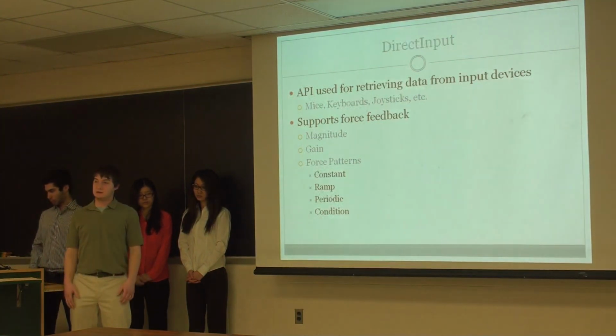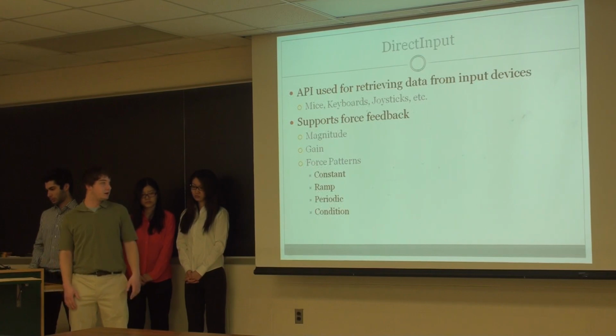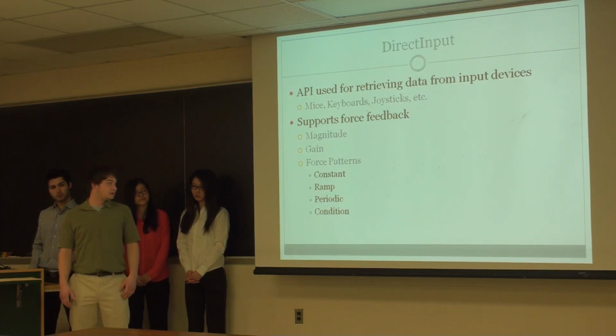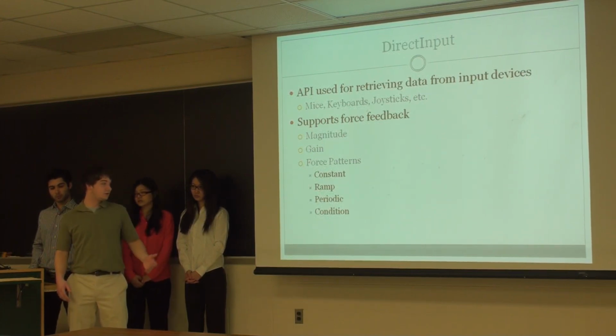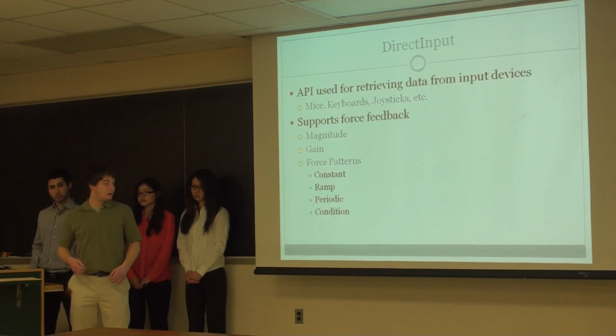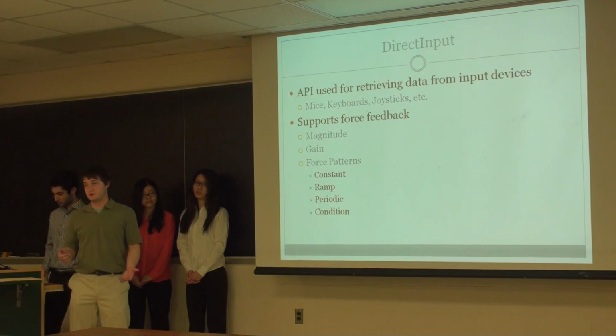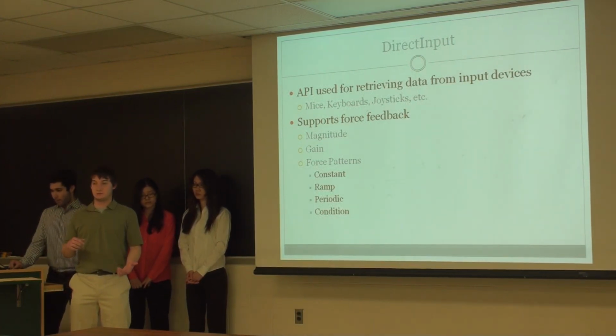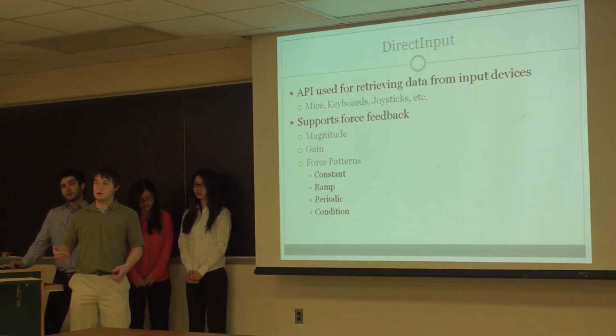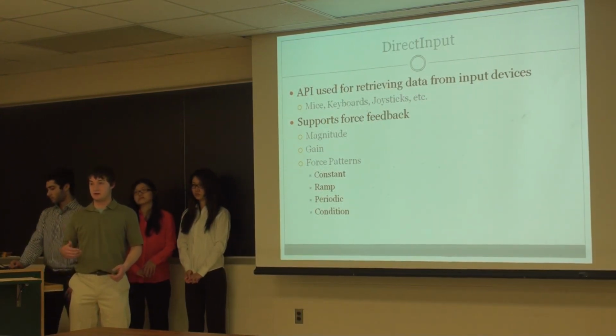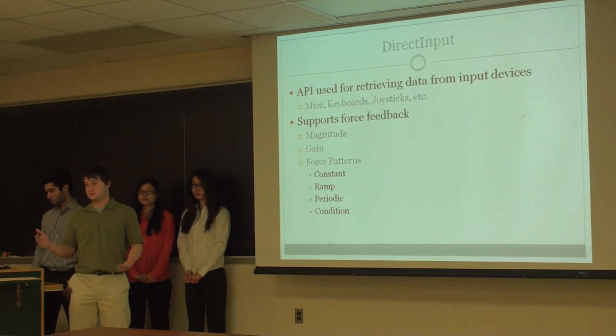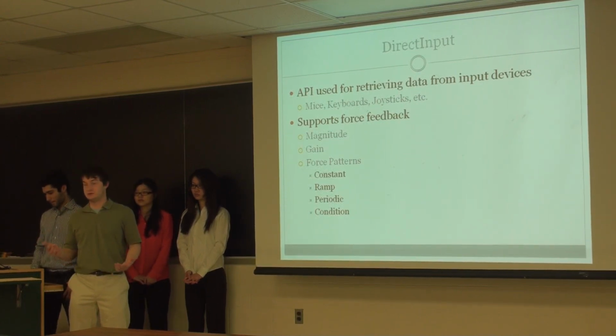You can also assign different force patterns. It's not limited to a constant pattern. There's actually ramping, periodic, and condition, just to say a few. Condition is probably the only kind of ambiguous one up here, so I'll explain it. Basically, a condition force is a force in reaction to a movement of the joystick. So say, for instance, you move the joystick to the left. The condition force you can set to say, okay, when the joystick is moved to the left, apply a force in whatever direction, at whatever magnitude you choose.